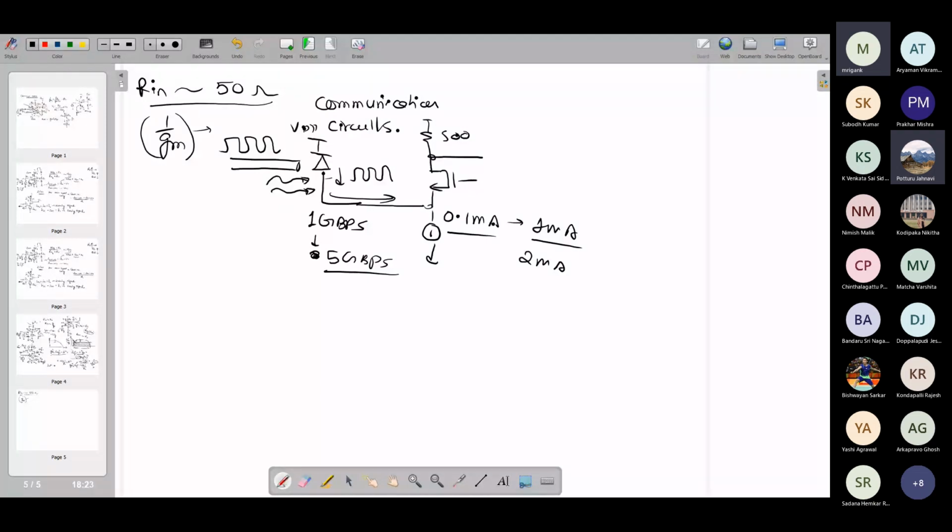The main thing is you have to make it work for high frequency. The photodiode may have its own capacitance, as high as 1 picofarad, and its own effective resistance as well, say a few kilo ohms. Then you have to model it as a current source, simulate, and find out the maximum bandwidth you are able to achieve. And this is one example.